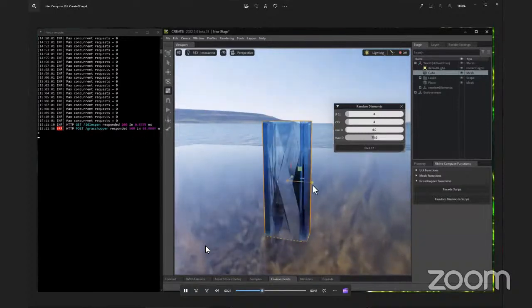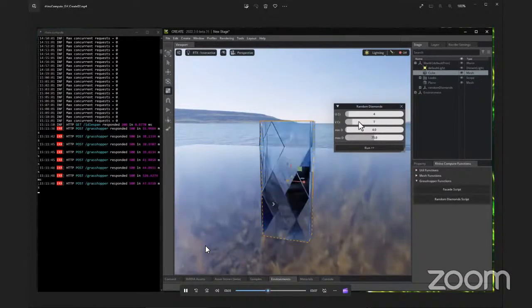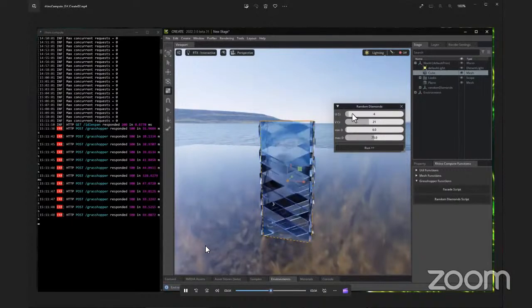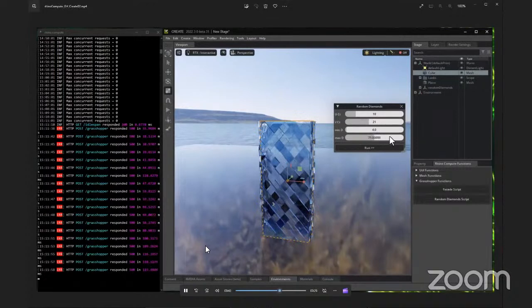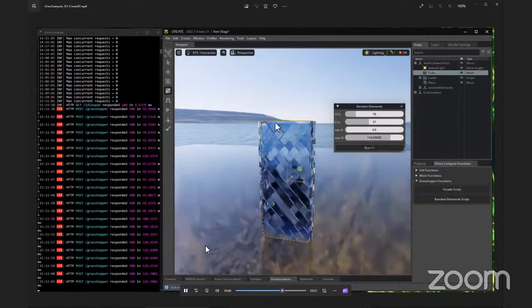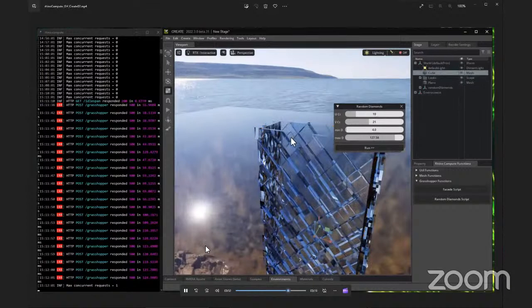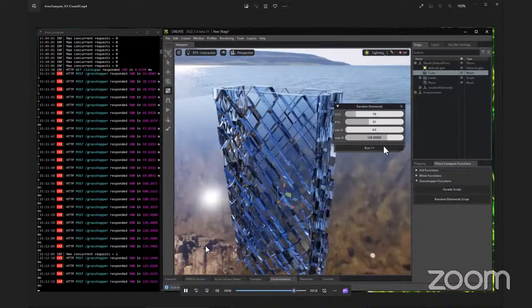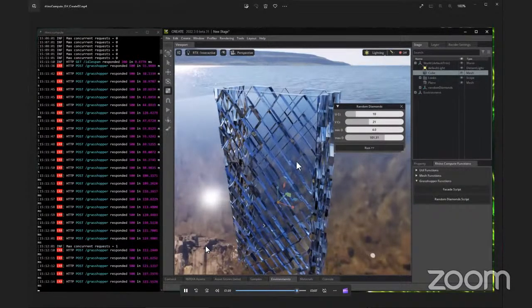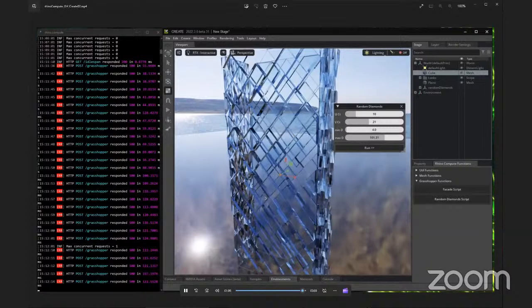So basically we have the Grasshopper script and the Compute server running, and now we're running through sliders inside of Omniverse, and it's computing in the background, just triggering a Grasshopper script. This is very, very simple. But the big thing is, since you have full Python support, being able to do these kinds of integrations is actually quite straightforward if you understand how to do a Rhino Compute integration, mostly because Rhino created such an amazing API. So, yeah, unpacking the inputs, turning them into UI controllers, and then being able to run Compute directly inside.